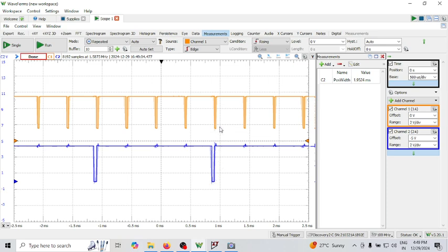Now when your next trigger signal comes after your output has gone to the stable state, only then the trigger is valid. So this is a valid trigger signal, whereas these are not valid trigger signals, even though they are less than VTL. Why they are not considered valid is because at that time the output is not in the stable state.